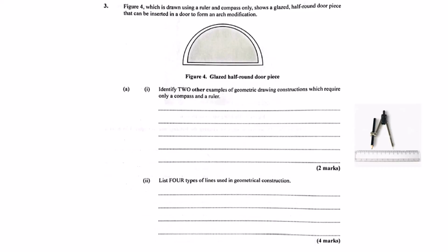What about those dashed lines you sometimes see, the ones sort of tucked away? Right. Those are hidden lines. They show edges or features of the object that you actually can't see from your current viewpoint because they're hidden behind another surface. Imagine looking at a box. You see the front edges, right? The hidden lines might show you an edge on the back, out of sight. And you really don't want to mistake a hidden line for an object line during construction.